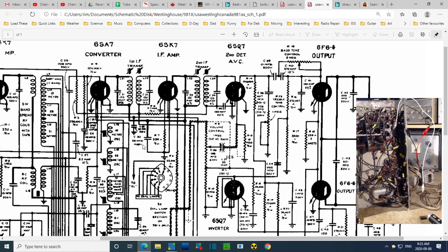Okay, this be the guy. And it's 0.2. There you are. C30, 0.2, 400 volt. It's exactly what's there. And what is it doing? Oh, it's got a very important job here of trying to provide a signal ground at the bottom of this coil. And this one too. So if this capacitor is not capacitoring very well, if it doesn't have much capacity, then you won't get a ground here. It can only weaken this whole thing.